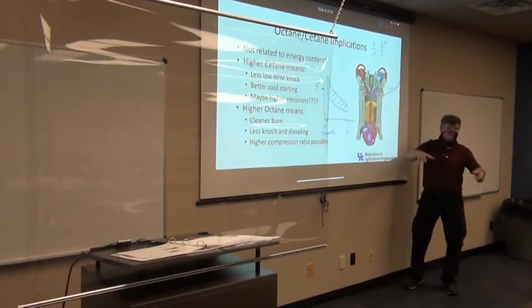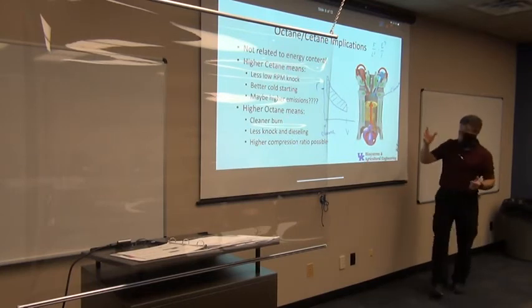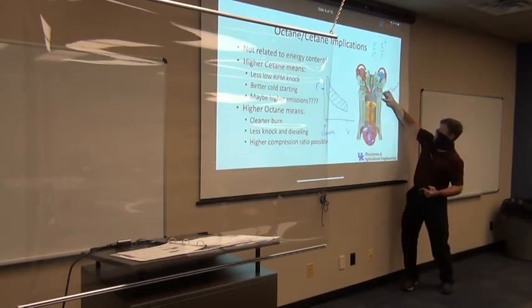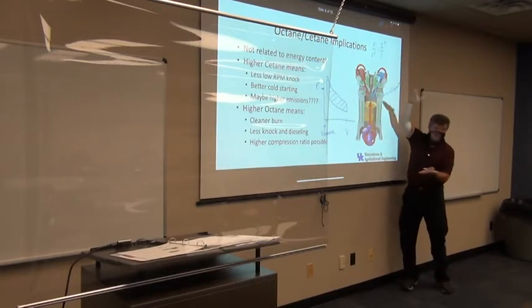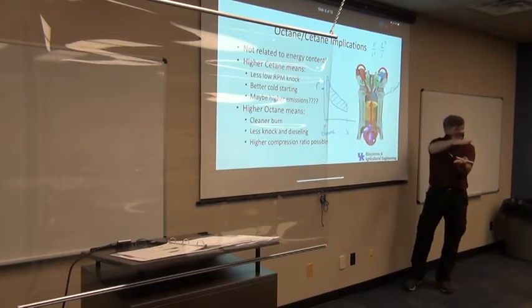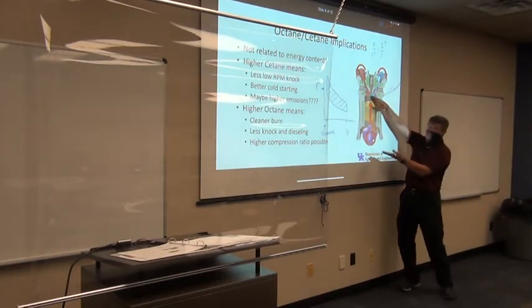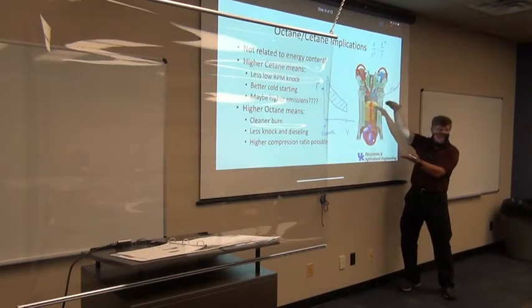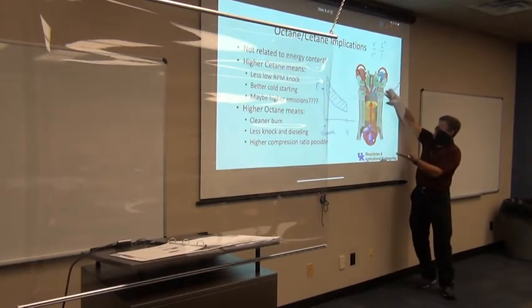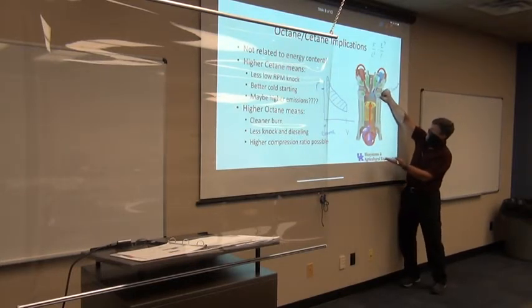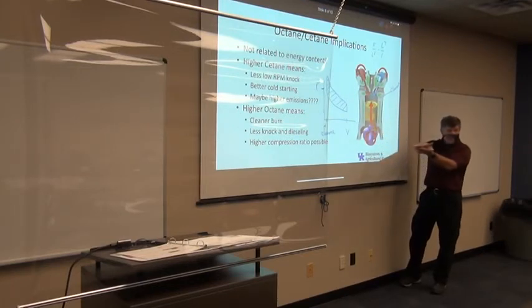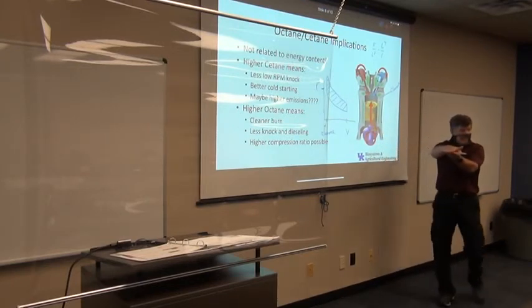We would take the heads off of the engine, put them on a machine tool somewhere, and physically machine some of the material off of that head. So when you put the head back on, what does that do to what's going on inside of the engine, to the displacement, to the clearance volume, and all that? What's going to happen? If I shave that head, take a little bit of material off the bottom of this, so when I put her on, it's down closer, what's happening?